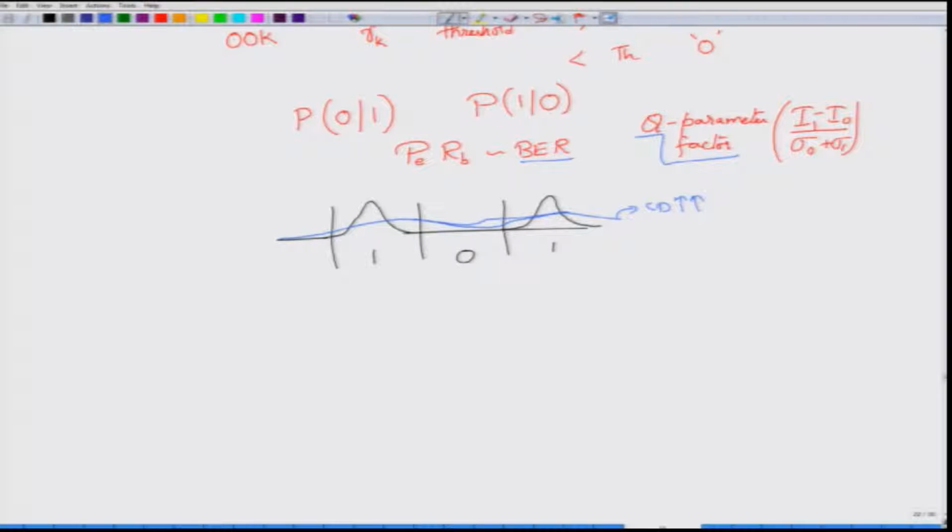So, to analyze the effects of chromatic dispersion on the pulse, we look at the rise time of the pulse, the transitions from 1 to 0 and 0 to 1 when you have chromatic dispersion, also when you have noise, and whether all these symbols are coming in at their corresponding bit boundaries. For example, in one time you have this particular bit boundary, signals are arriving within that, next time there might be a small delay. So, you might not have a large amount of chromatic dispersion, but then you have a small delay, and this delay can be either earlier or later.